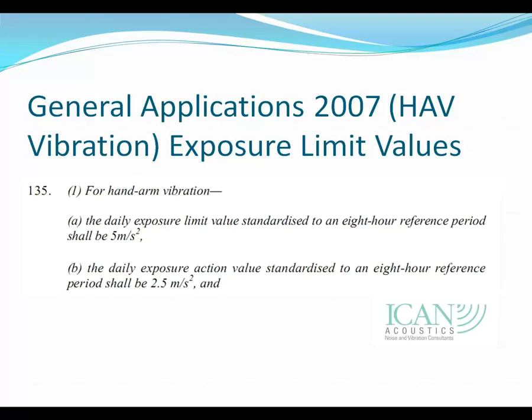So for example, if you had a powered hand tool, you would be concerned with, we'll call it, the trigger on time. For example, if you take an individual using an orbital sander at a facility, it's unlikely that an operator will use that particular piece of equipment for 8 hours solid. You're talking about work breaks, rest periods, and so on. So again, it's based on the likely exposure over an 8-hour period, and in some cases that might be as low as 5 or 6 hours per day. So you need to keep that in mind. It relates to the on time of that equipment.